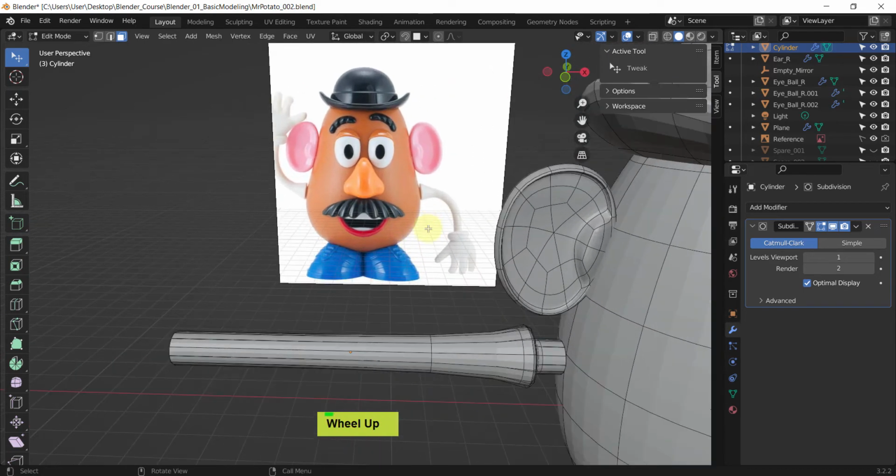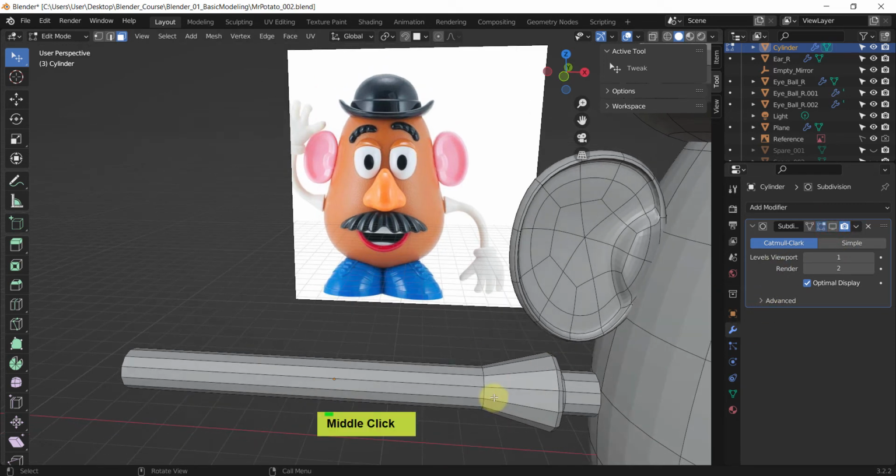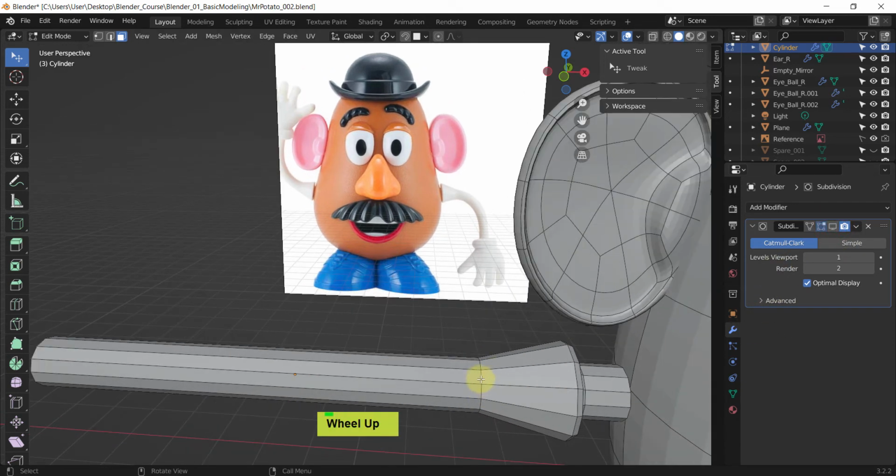Okay, one thing, the transition from this conic shape to this cylindrical shape is a little bit sharper than here. It's more transitioned, so for that we need to emphasize this edge area. So let me turn off the visibility of this one, and to strengthen the transition, edge mode, Alt and Control B, and divide this edge.